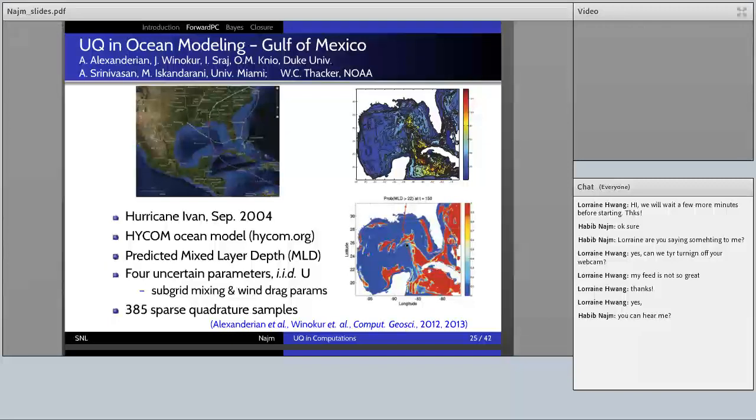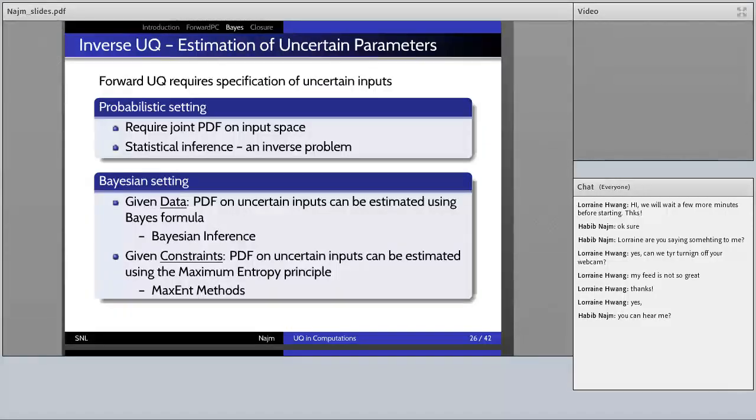So V0 is the mean velocity field, and the flow is going vertically up here. So it's like a starting flow in a rectangular channel. So you will get an initial startup phase, and then you get the fully developed flow, which stabilizes further downstream, which is towards the top. And the individual modes are shown to the right.